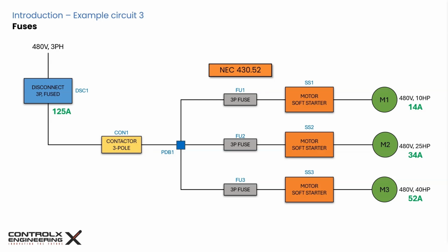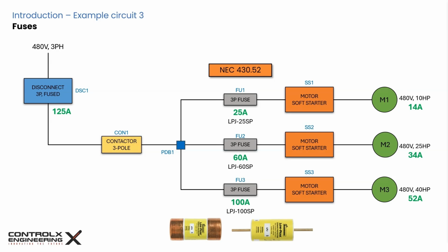For motor protection, time delay fuses allow for high inrush current while protecting against short circuits. Fuse rating is based on motor FLC and based on NEC Table 430.52. The fuse size can depend on the motor type and permitted percentage of FLC as per Table 430.52. Based on the table in NEC 430.52, these are the recommended fuses. Select the appropriate 3-pole fuse holders for the selected fuses.